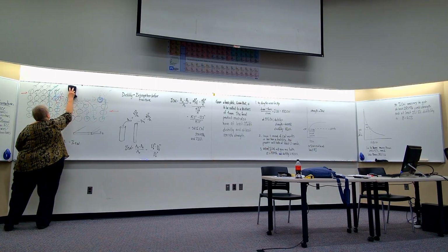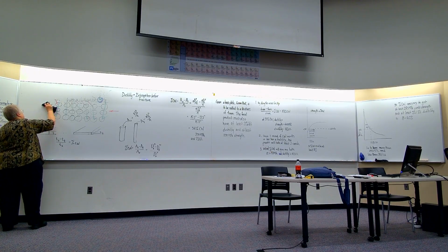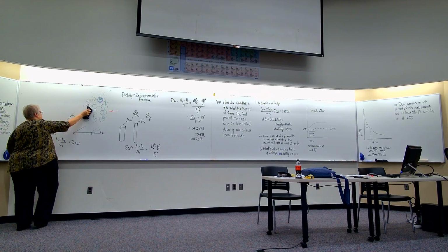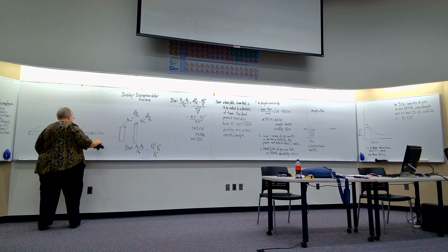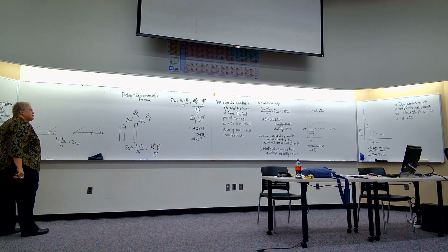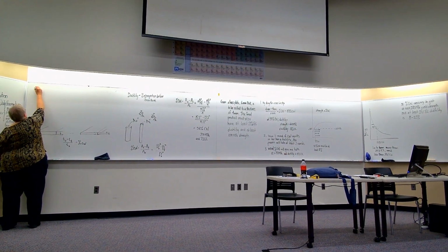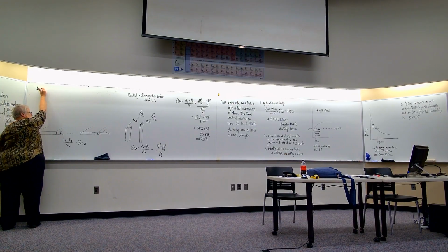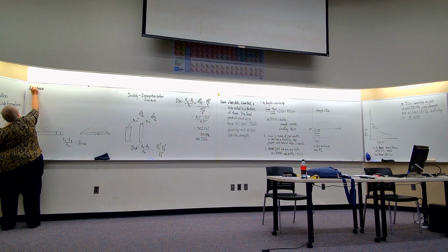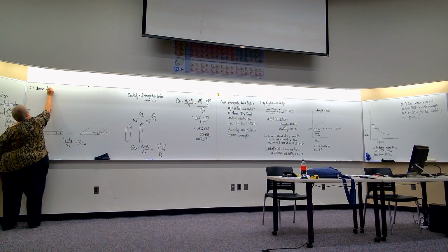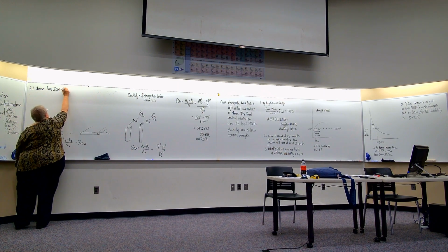Usually, if I don't want to have to spend a lot of rounds getting my desired properties, I'll choose something on the bigger side. So let's say, I'm not going to go with 20, let's say we go with 16. There's nothing magical about that number, but I chose a number between 8 and 20. Final percent cold work as being 16%.